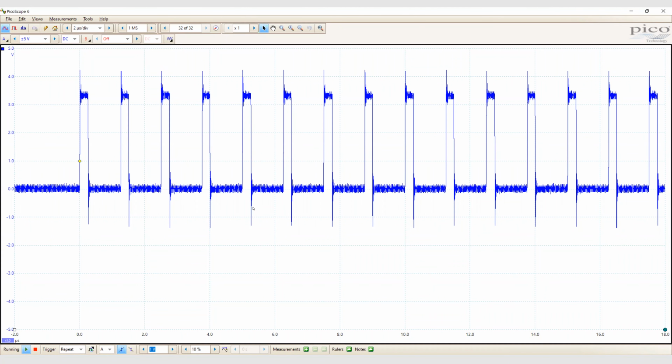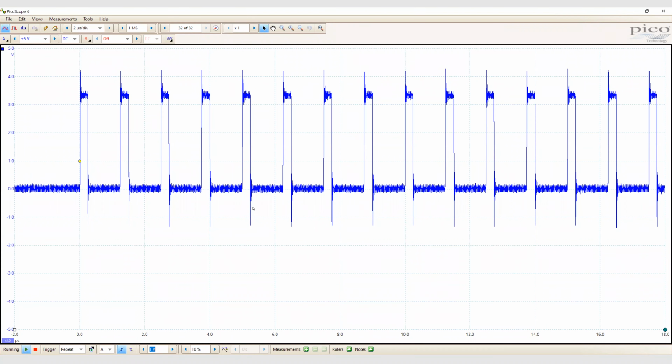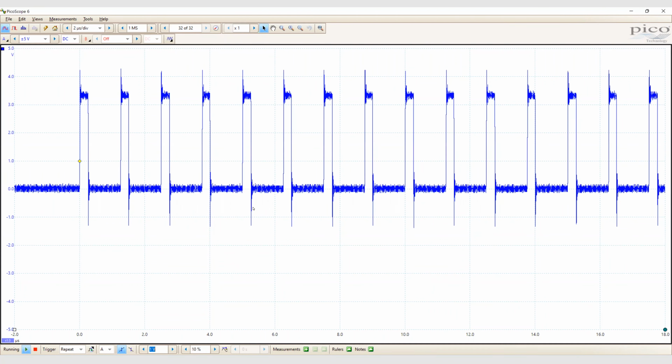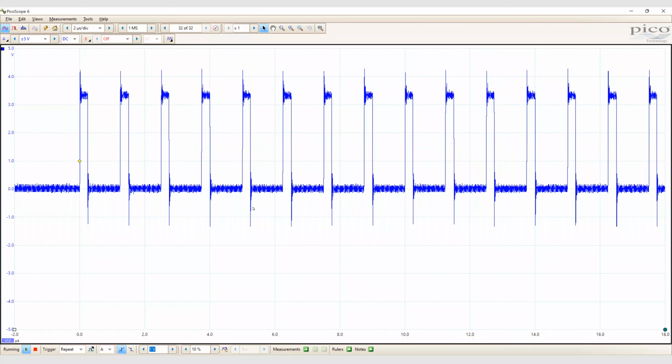There are different ways you can turn bits on and off with the Pico. One way is you can just do what we did in the first class, where we just GPIO, turn it on and off. And that works fine. The problem is that you use the entire CPU doing it. So usually you want to do other things. For example, if you want to do the IR to LED, you would want to do this at the same time. That's when the projects get really interesting.